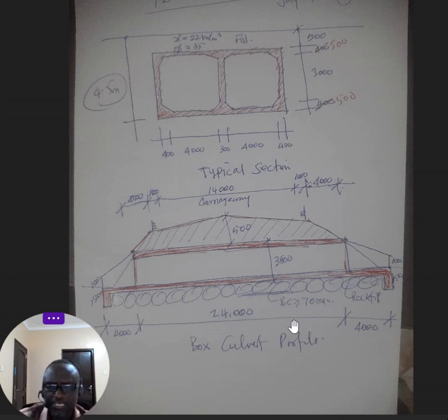Normally this rock fill, you don't just dump it. You need to be aware so that you guide it, and even quantity takeoff, and when it comes to audit and you want to check certain things, you are certain that the quantity surveyor is not going to give you an arbitrary volume. You must have a basis to determine your volume. Now, this is where you look at economy. You're not just going to throw in 70 trucks of rockfill in a place of 2-3 box culverts.